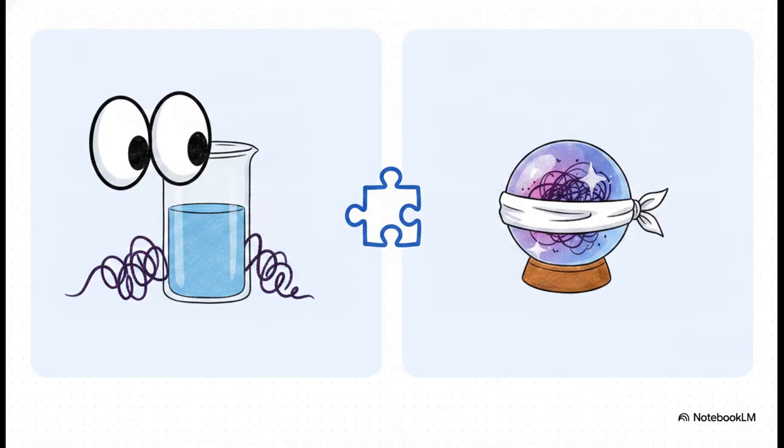And this brilliantly illustrates the core difference between these two foundational strategies. Just look at this side by side. Feedback measures the controlled variable but completely ignores the disturbance. Feed-forward, on the other hand, measures the disturbance but ignores the controlled variable.